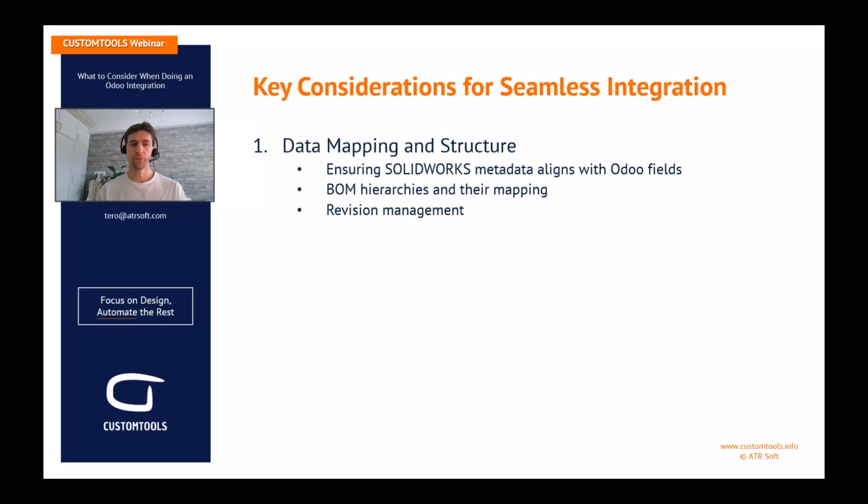In CAD, you produce an engineering BOM, and typically the BOM structure is driven by how the product is most convenient to design. In an ERP system, on the other hand, you use the same BOM or list of components to buy them as standard components, buy them from a subcontractor, or make them on the shop floor. You may store sub-assemblies in your warehouse. Many times, the engineering BOM needs to be translated to a manufacturing BOM in the ERP system.